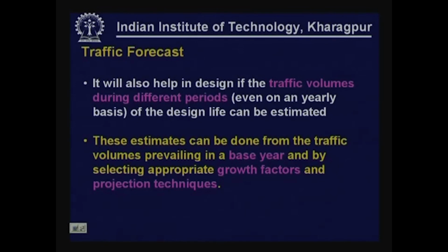It will also be very useful in the design if the traffic volumes can be estimated for different design periods. Rather, if the total design period is 20 years, what would be the traffic volume during the next 5 years, next 10 years, next 15 years? If we can have predictions that can be made for different sub periods of the total period, that will help us in making various strategies like going for high initial cost, different types of maintenance strategies at 5 years, 10 years intervals, or other strategies which we can make based on how the traffic is going to be distributed over the entire design period.